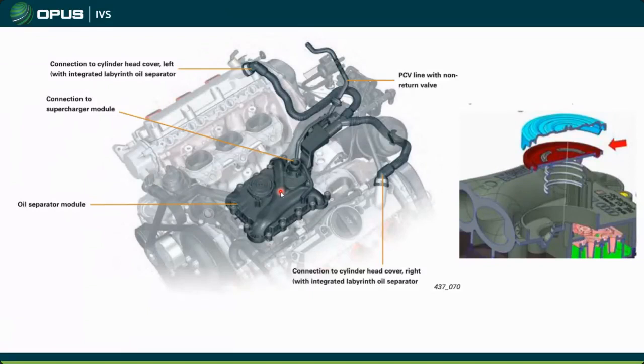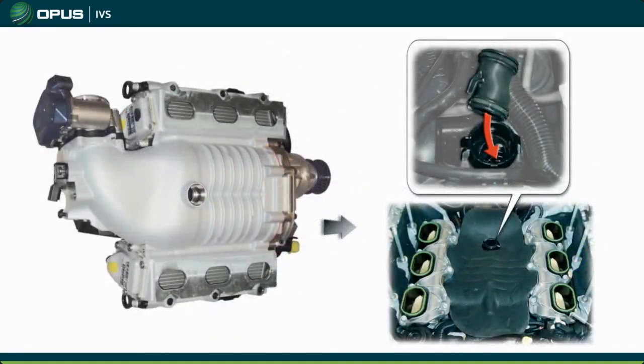Now these also had a very similar issue with oil consumption, and we replaced these a lot too. A very similar circumstance: you would replace the valve, and you would have to update the ECM to tell it that you've reduced the crankcase pressure. This picture, I just wanted you to see that there is the connecting piece that vents into here.